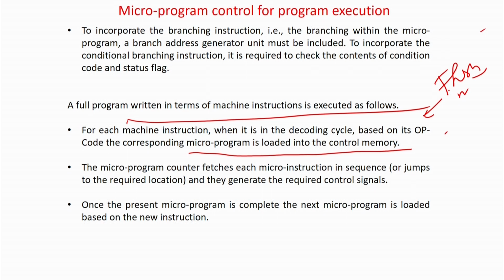After that, there is decoding. So, once the decoding cycle is done, the corresponding MPC points to the memory of the microprogram which corresponds to that particular instruction. If there are multiple instructions like add, sub, multiply, for which we have made a single code to optimize space, then for any of these instructions you start pointing to the start point of that corresponding instruction.